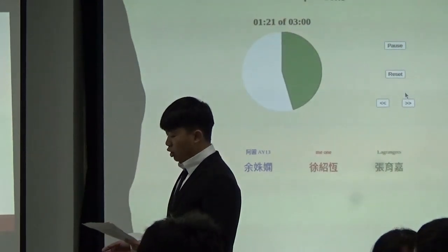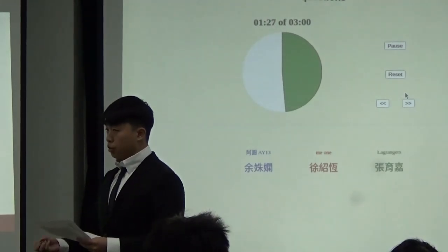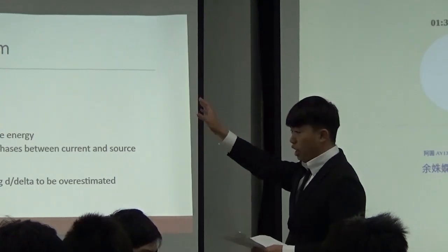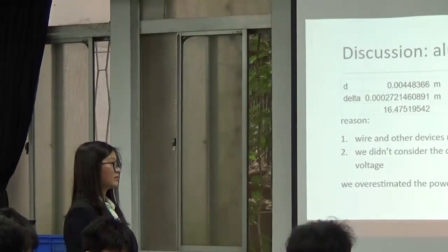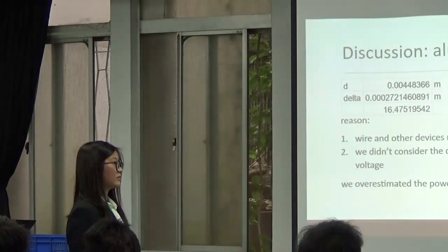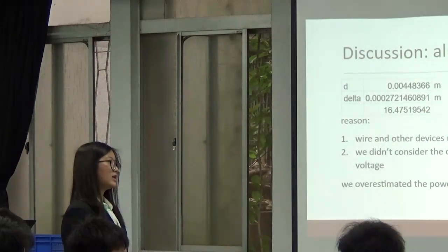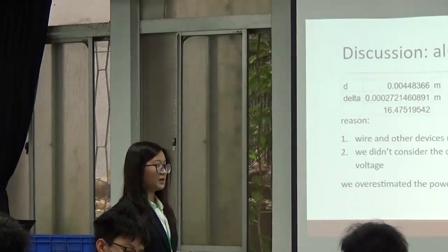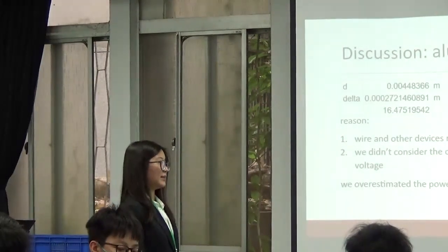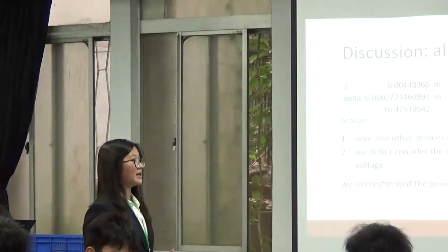When you put the aluminum rod into it, which factor, which number changes the most? Like you have many theories, and there are a lot of numbers in it. Maybe voltage changes the most, or maybe frequency. I don't know. So I want to ask you, what changes the most and makes you think that it is aluminum? The result of air and aluminum will be different because of the conductivity, because aluminum is metal, and we can know that it's not because of the permeability, because the permeability of air and aluminum are the same.